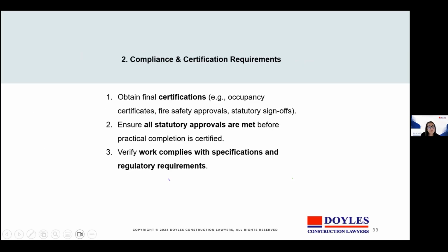And number 2, compliance and certification requirements. So statutory compliance is non-negotiable. And without it, it's often that practical completion cannot occur. And so this would involve obtaining all final certificates, whether it's occupation, fire safety approvals and statutory sign-offs, ensuring all statutory approvals are met before practical completion is certified, and verifying the work complies with specifications and regulations.